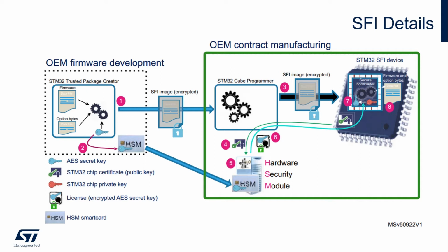As we will describe in more details in the following section, the implementation of the STM32 Secure Bootloader used in SFI configures the onboard STM32 security features to protect access to the user flash memory or the SRAM, and therefore preventing the OEM code from being extracted or disclosed during the whole process.